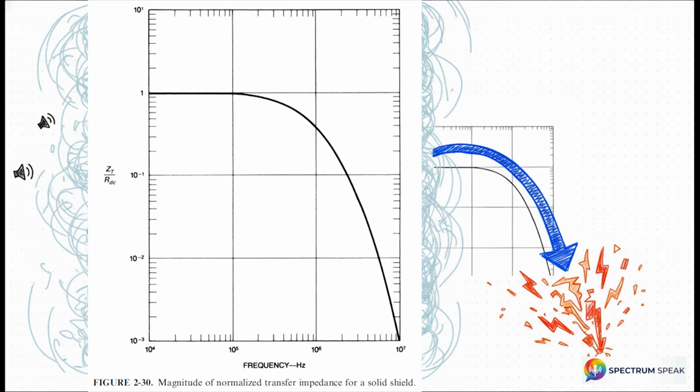Notice the sheer contrast between our options here. Over on the left, we've got a raw, unshielded twisted pair, which is incredibly common and honestly surprisingly robust if it's perfectly balanced. But look at that graph on the right. This curve represents transfer impedance, which is essentially a cable's vulnerability to noise plotted against frequency. Notice how that curve suddenly bends and just drops straight off a cliff as the frequency rises? The stakes here are absolute. If you choose the wrong cable geometry without understanding this curve, your noise immunity doesn't just degrade gently, it catastrophically fails exactly when your system's frequencies ramp up.